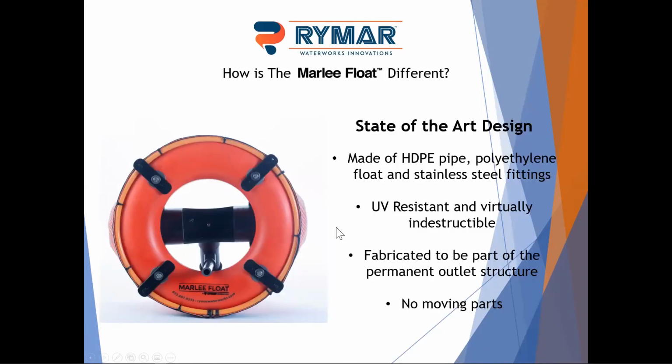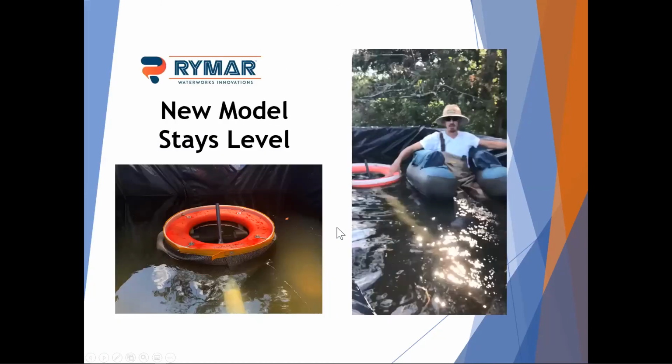So the other thing that's a little bit different about the Marley float is its construction. It's an HDPE product, a polyethylene float with stainless steel or aluminum fittings. So it will not rust, it's very UV resistant, and honestly it's virtually indestructible. It's an extremely durable product. We've had one get blown through a dam in a hurricane, and they picked it up from 100 yards downstream and put it back in, and it worked fine. It is designed to be part of the permanent outlet structure, and has just one pivoting part, really no moving parts to get stuck or cause any problems.